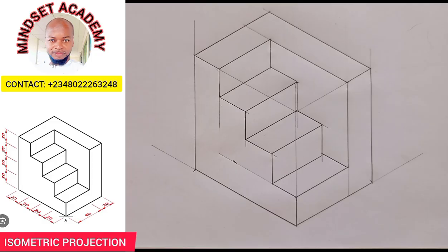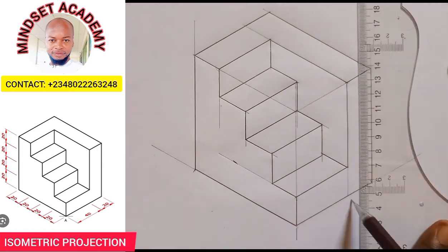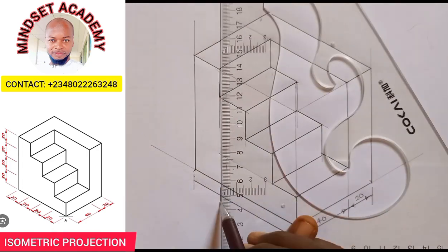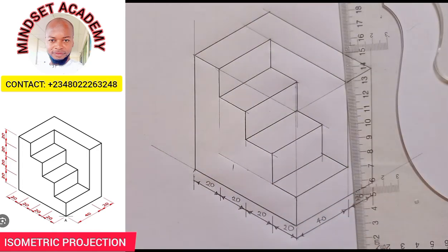Your dimensioning is always very important. Ensure that your dimension line is not touching the main figure, right, and your numbers are not resting on the lines. They should be a little bit spaced.